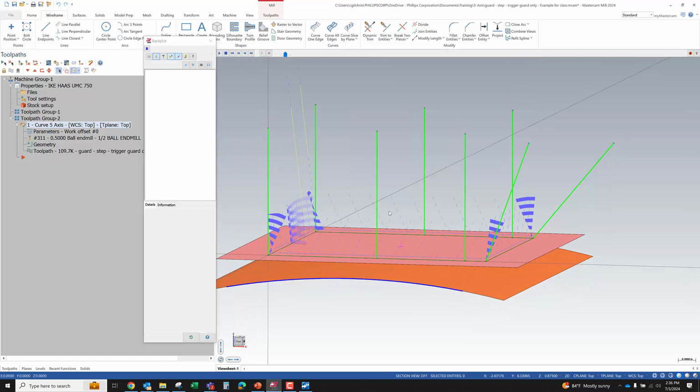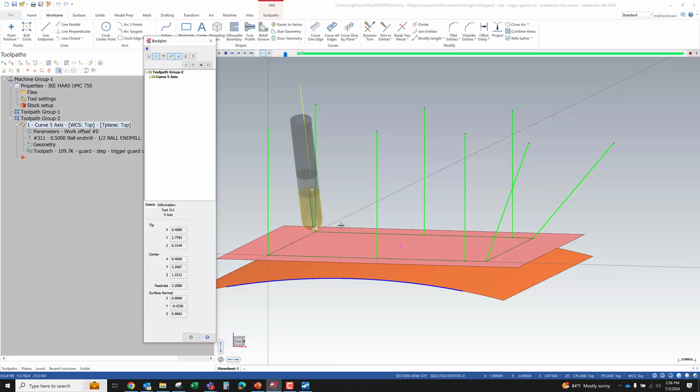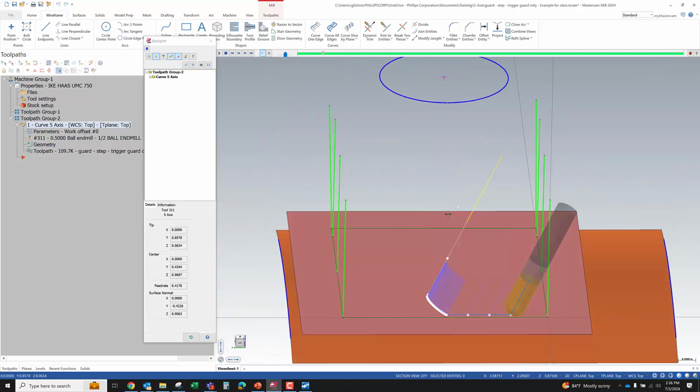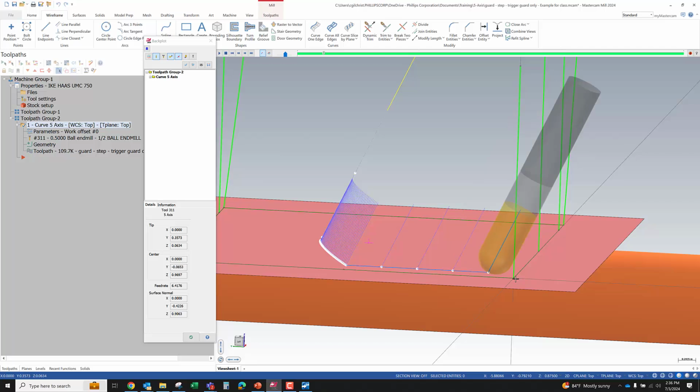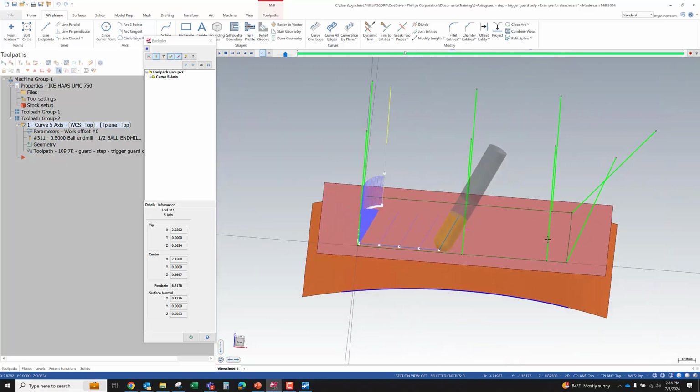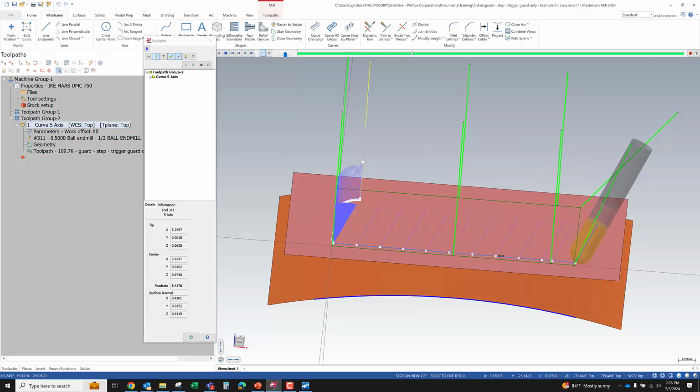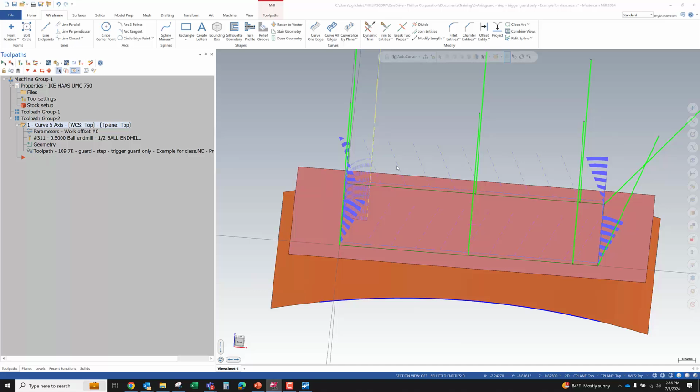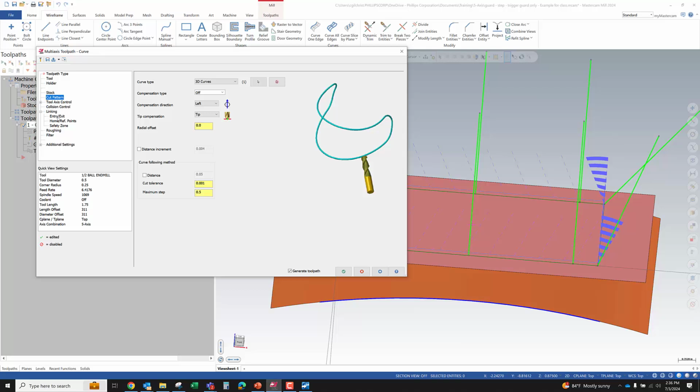So we're entering in, and we're already tilted forward. So now it's got to figure out how to do the transition. This gets to be a little awkward because we're using lead and we've got a sharp corner in here. It just has to figure out how to do that transition. Now, would I run the path specifically like this? No, probably not. But I'm showing you kind of what's available. And sometimes even, say, a 10 or a 15-degree lead or whatever angle change, right?